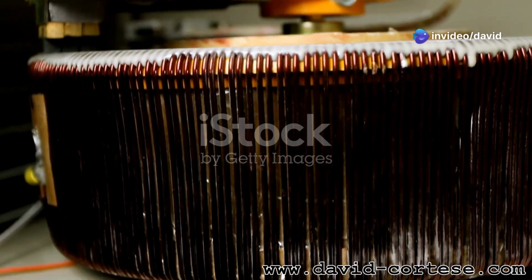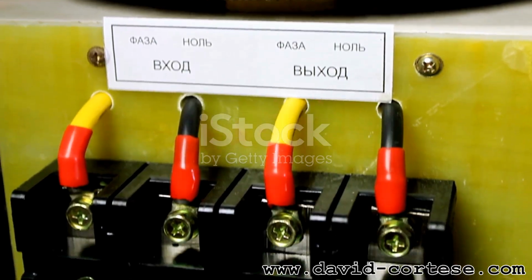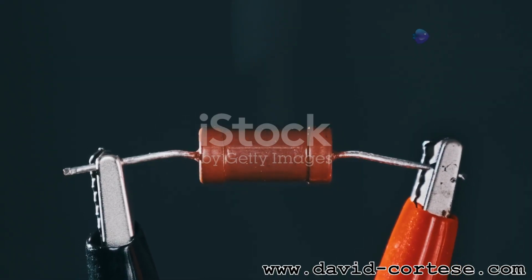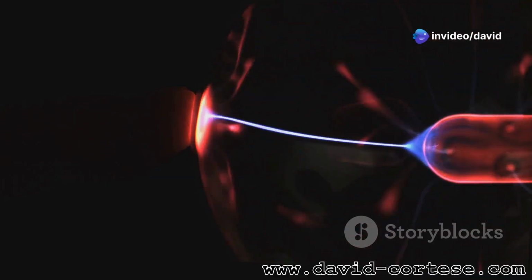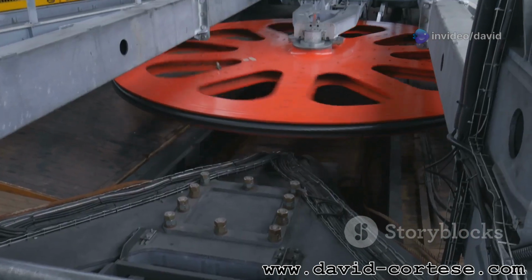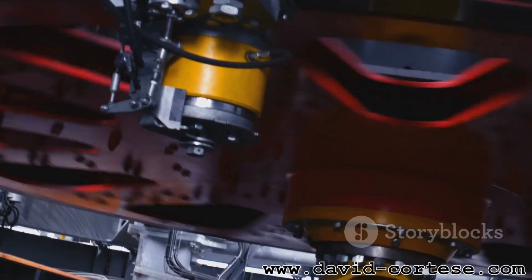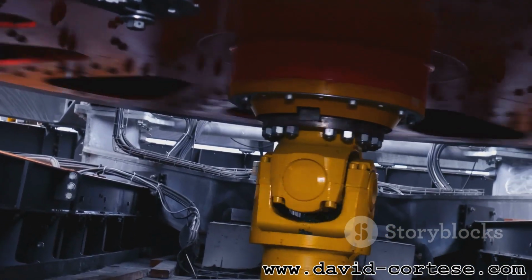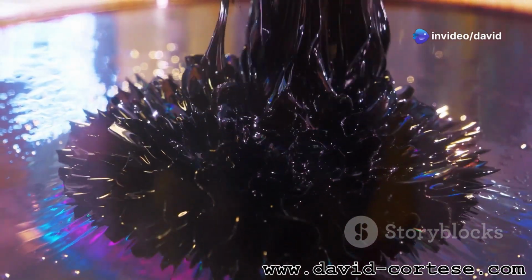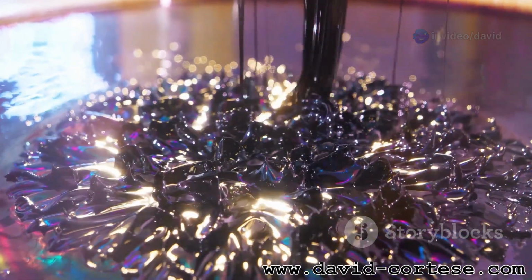Inductors, often coiled wires, possess the intriguing ability to store energy in magnetic fields. Unlike resistors, which resist the flow of current, inductors oppose changes in current. When current flows through an inductor, it creates a magnetic field around it. Imagine an inductor as a heavy flywheel. Just as a flywheel resists changes in rotational speed, an inductor resists changes in current flow. When current tries to increase or decrease, the inductor's magnetic field either expands or collapses, opposing the change.